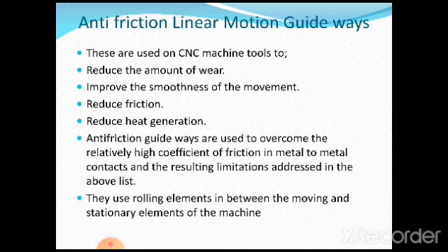Let us see. Definitely compared to the linear bearing with balls, where there is a point contact, in the case of a linear bearing with rollers, there is a line contact. Definitely it has a better loading capacity. So this arrangement provides smooth and easy movement, but the machine bed has to be machined to an accurate form. So whatever the machine bed formation is, it has to be machined correctly.